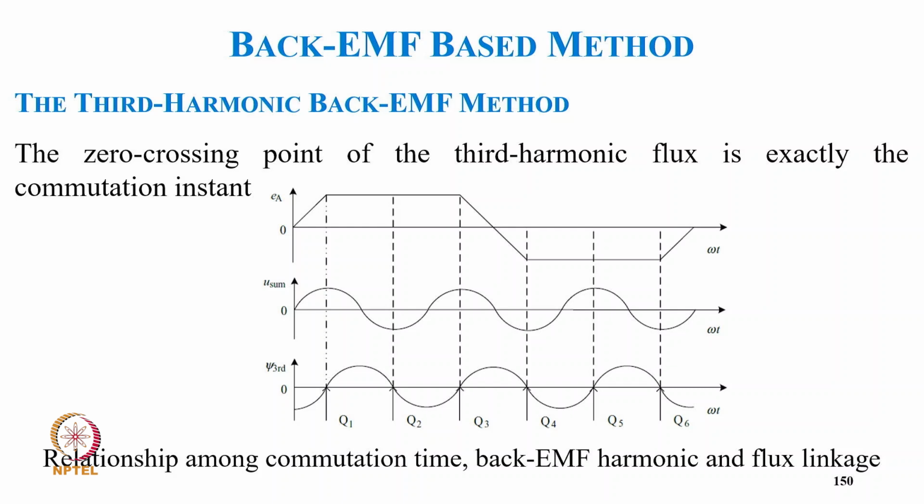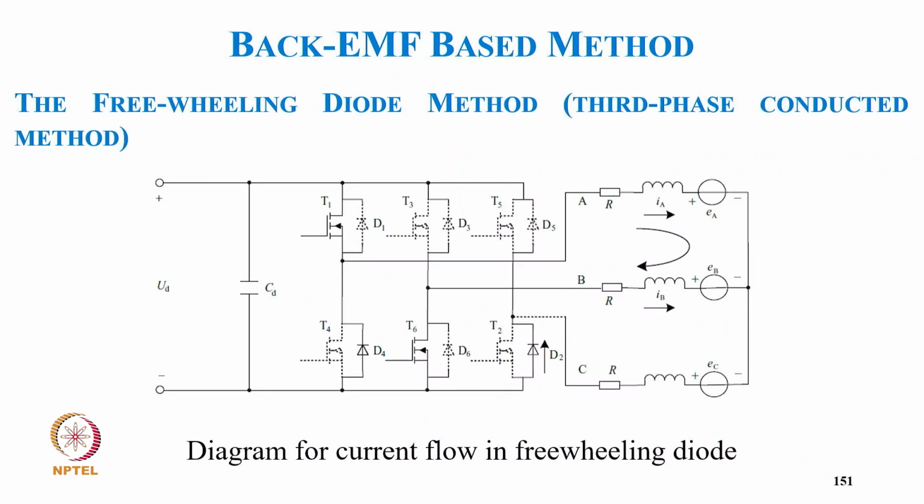So the integration really takes care of the actual zero crossing required typically for phase commutation. So this is the relation among the commutation time, back EMF and third harmonic flux linkage.